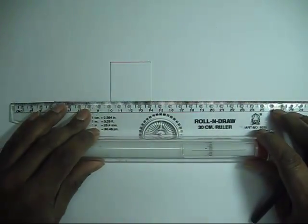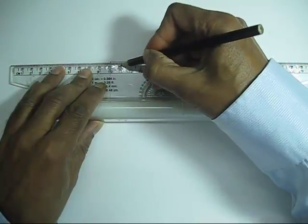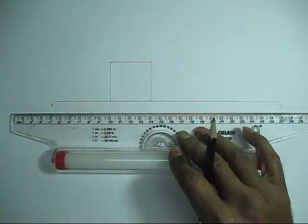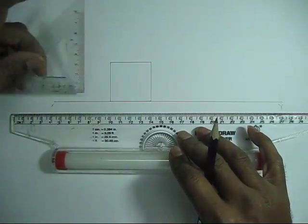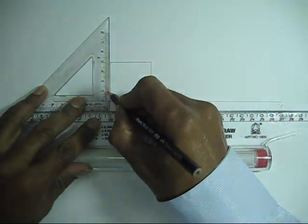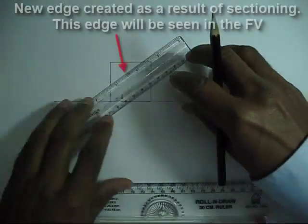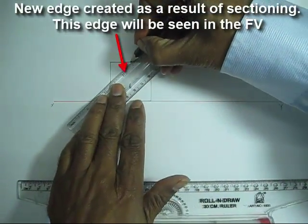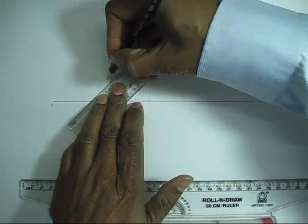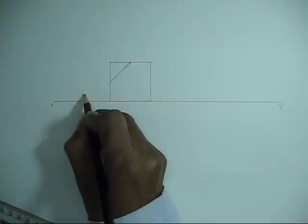This inclined edge cuts two sides midway, so we will find the midpoints of two sides. This is the new edge which has been created as a result of sectioning, and this edge is visible in its true length.